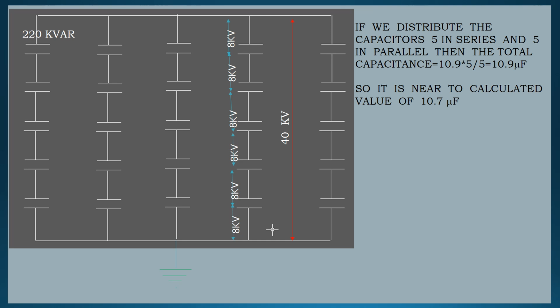You can increase the capacitance more because nowadays the meter is not calculating the leading power factor. So if you add more capacitors, the leading factor will arrive and again the power factor will come low. But now it is ignored, so we can add more capacitors to reduce the penalty or stop the penalty.